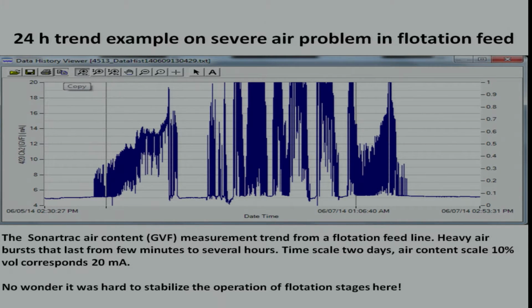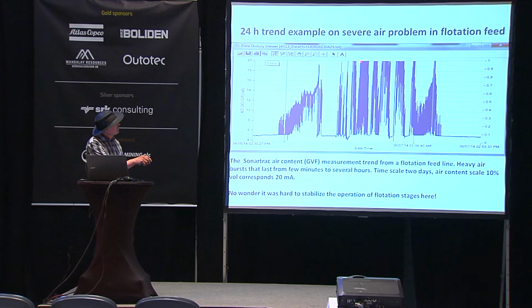If we look at this, this is a 2-day trend, and you can see that the air content has gone up even over that 10%, which has been set to correspond to the 20 milliamp output in this process. So for hours, there has been up to 10% air going into the flotation tank. No wonder it's difficult to stabilize the operation of that.